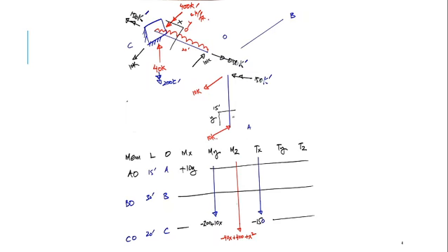Okay, so this has been done. Next, the section is X and I have to find all the moments here. This point, at the left, is 150 kip-foot and this is anti-clockwise in X, so it has to be balanced with the equal and opposite torsion TX, and this would be negative because this is anti-clockwise. You should know that this is an anti-clockwise in X, so this is 150 pure moment, so it has been mentioned as it is.